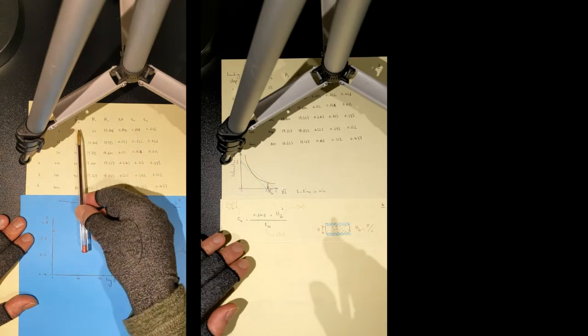So you have a data set. You have sigma dash, effective stress, versus e, void ratio. Look at this. Void ratio on the vertical axis and sigma dash on the horizontal axis. And you can see that I have a number of data points all here. Now, I remind you that these void ratios are void ratio at the end of each step of loading, and sigma dash is effectively sigma dash 2.